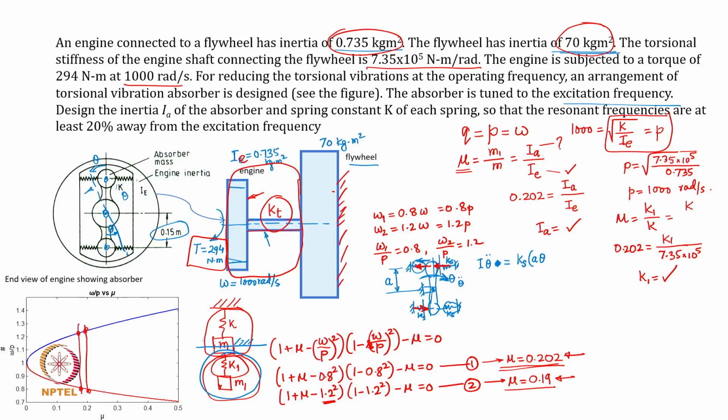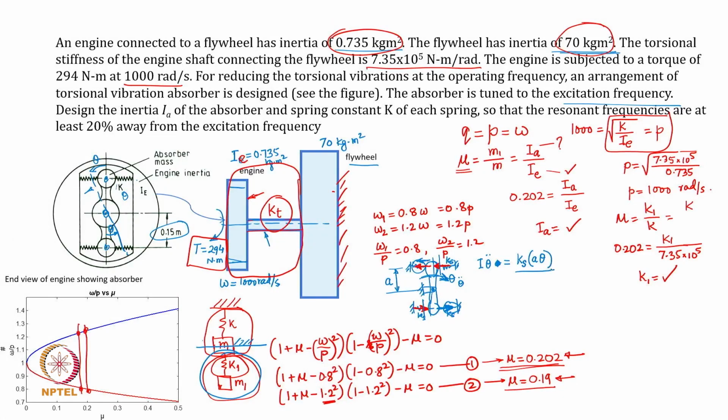Likewise, you may very clearly see that all the springs are going to generate a counterclockwise restoring force on the link. The moment the link tries to turn clockwise, all the four springs are going to try and tilt it back to its original position, and the force value is going to be the same, Ks into A theta. Ks is the spring stiffness at all these four contact points, and therefore the force is going to be 4 times Ks into A theta. The combined effect of all the 4 springs can be this much.